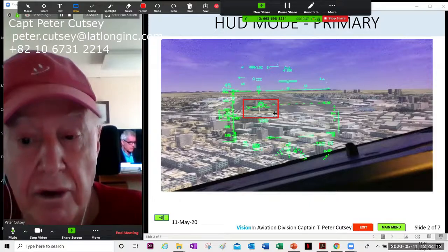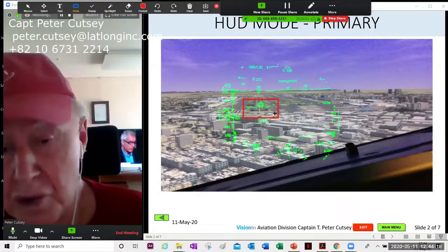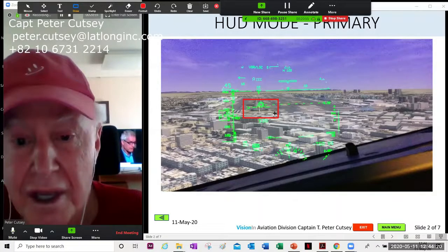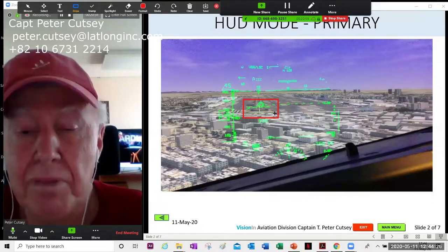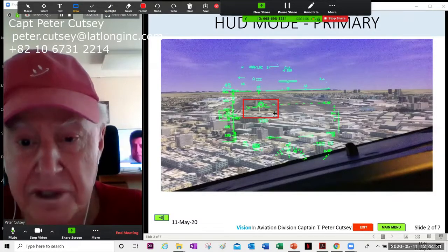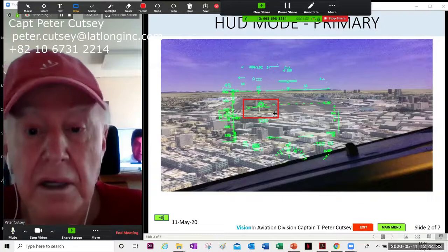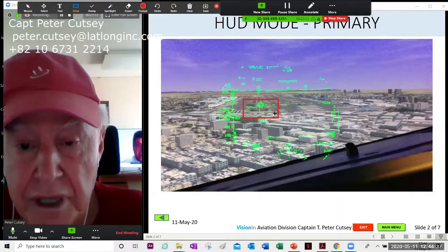The other very important thing about when a pilot flying, of course, is using the HUD, the pilot monitoring is not using the HUD for obvious reasons. His or her head must be on the flight deck. So your pilot monitoring's duties are highly enhanced because now there is only one set of eyes on the flight deck to monitor engine parameters and everything else.